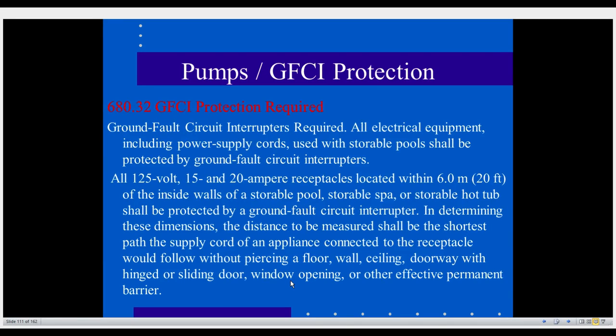And so they're saying, well, it might be the living room receptacle, but it needs to be GFCI protected due to the location of the storable pool. And of course, that's not the case. It's through the opening, and the opening can be shut. So the measurement is not to penetrate the opening like that. Okay. So this only applies to receptacles that will be outdoors or out near the storable pool.